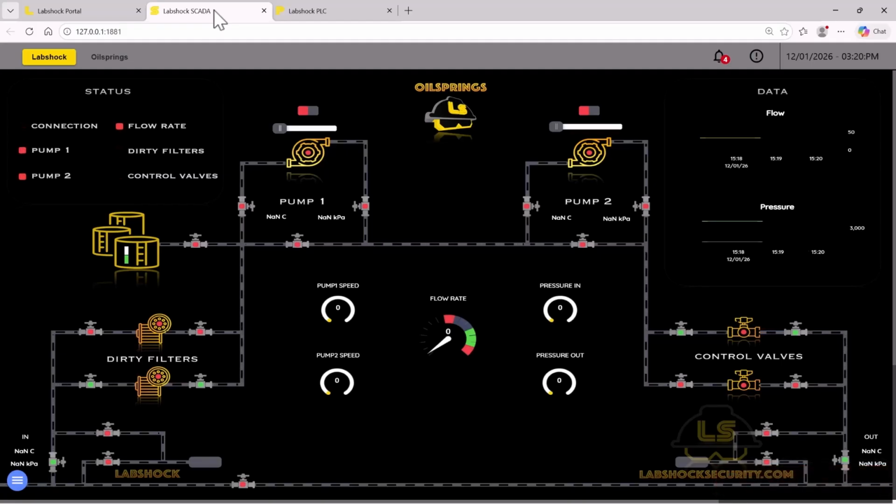So we can stop the PLC, and that's where we lose the ability to monitor and control through the computer systems. But then we have to ask, and of course, every environment and every process is going to be different, what's going to happen to that process when all of a sudden the PLC essentially just disappears? So keep that in the back of your mind.